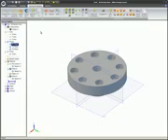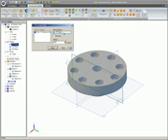To insert a section view, on the Viewing and Analysis ribbon, click on Section View and the 3D Section View dialog will be displayed. In the 3D Section View dialog box, there are a couple of different options you can select. Since this is only a part, the part to section will already be populated. This will be different for an assembly, however.